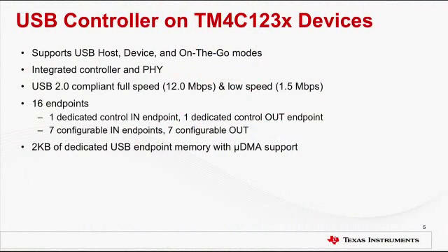The TM4C123X family of microcontrollers features an integrated USB controller with PHY. It operates as a full-speed or low-speed function controller during point-to-point communication in USB host, device, and OTG mode. The controller complies with the USB 2.0 standard, which includes suspend and resume signaling. 16 endpoints are supported, including 2 hardwired for control transfers and 14 endpoints defined by firmware. Also, there is a dedicated USB endpoint memory of 2 kilobytes with uDMA support. We will look at the USB module in more detail as we move along with this presentation.